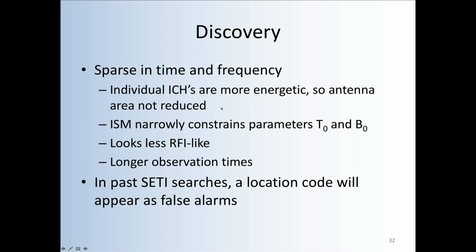Those advantages all accrued to the reduction in the average power of the transmitted signal rather than the peak power. But in fact, the technique I've described does not reduce the peak power. In fact, it generally increases it a bit, not dramatically, but increases it a bit. And it also does not take any burden off the antennas in terms of collecting that energy. So it's important to realize that characteristic.